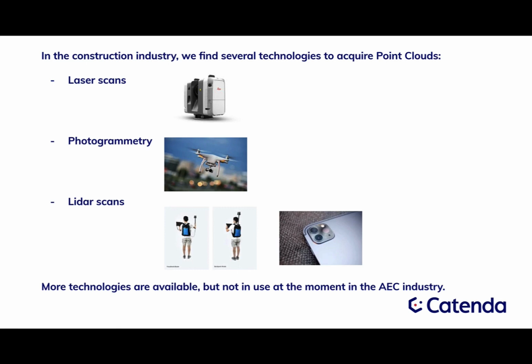Maybe most of you have seen that already, and if not in person, you heard about it or saw some videos about it. Another way to collect point clouds is photogrammetry. It's a very peculiar technique, and it involves a lot of back-end calculation, because it builds up a point cloud out of pictures taken in a specific way, where every pixel in a picture acts as if it was hit by a laser beam. So photons are basically used as lasers, and they represent the XYZ coordinates. So you need a lot of back-end processing to rebuild a solid or a 3D point cloud from pictures.